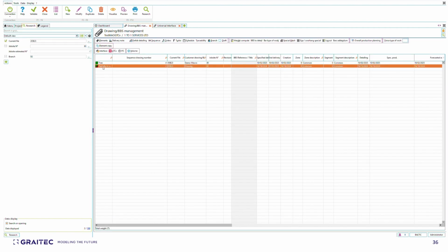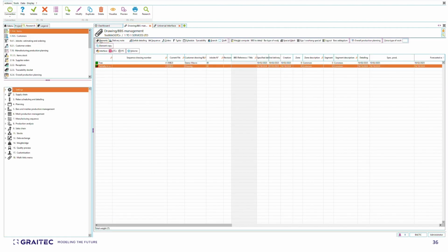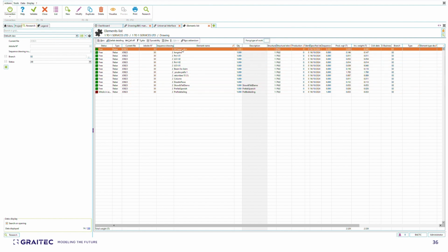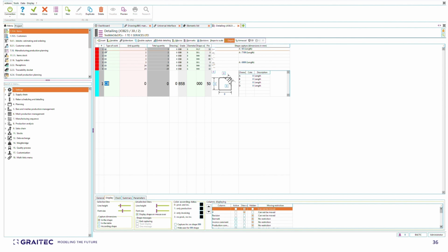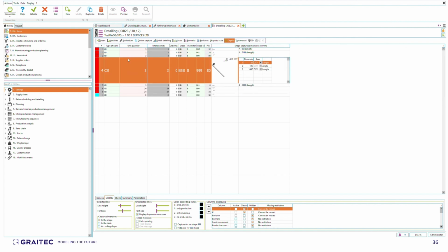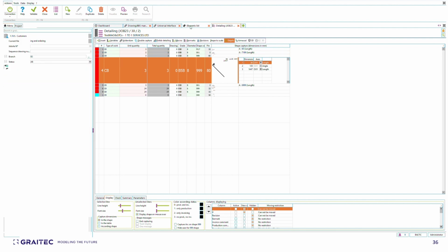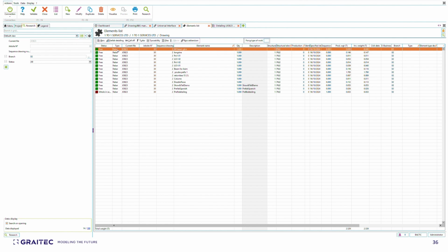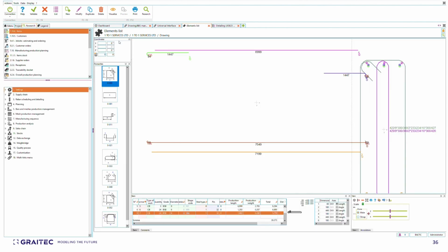As well we have the ability to show it in prefab detailing. So just to give you an example, if we go into elements again, we placed an AD beam, we can go into bars, and you'll have the list of rebars for this AD beam, so you can see all the bars that have been designed and need to be produced. We can also select that into prefab detailing and see how it's assembled.